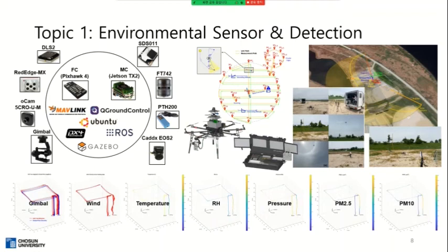Yes. Basically, I use MAVLink-based ROS, which is MAVROS. In MAVROS, when you run the rostopic echo command, you know that command, right? rostopic echo /imu/something. You can get any data from the Pixhawk. You can reach any actuators if you want. But I don't need to manage at that level, because I only need to hack the waypoint information and give a yaw angle. That's it.